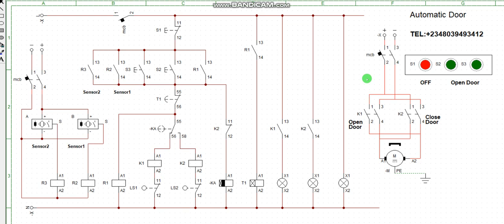If you are using single phase, there are terminals called capacitor line and capacitor permanent. These are the three terminals that a single phase motor must be terminated with to function. So you interchange capacitor line and capacitor permanent, swapping them outside the contactor.